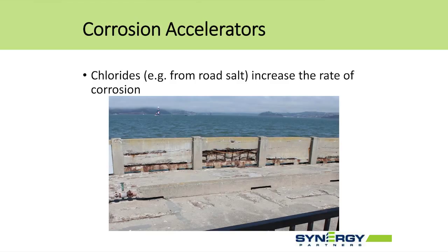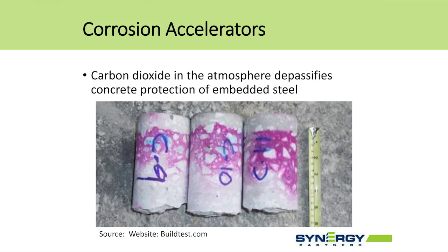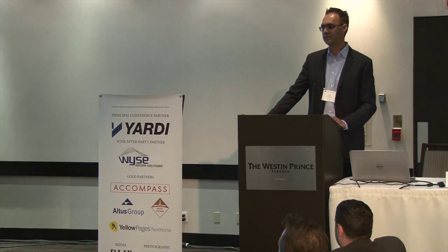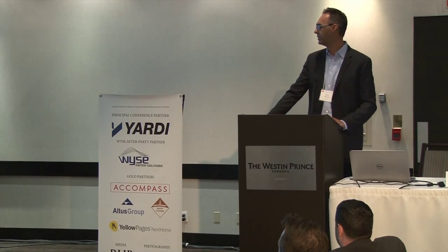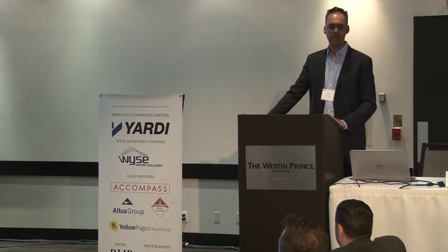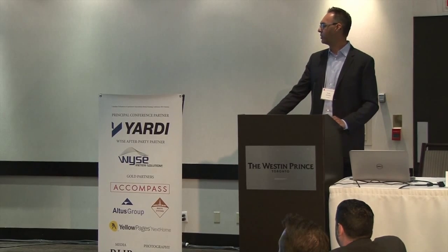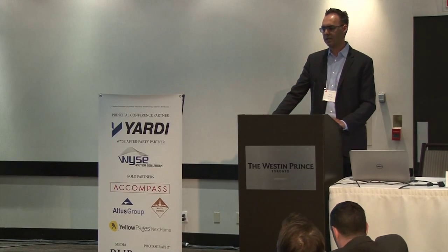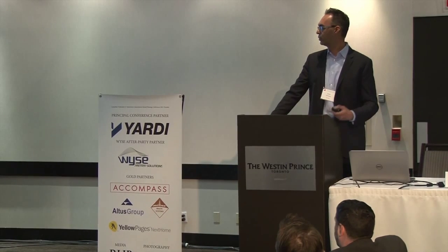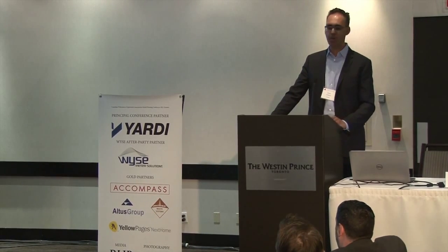Another process that you might not be so familiar with is something called carbonation. This is where carbon dioxide within our atmosphere can get into concrete and depassivate the natural protective cover that concrete provides on steel and cause corrosion as well. Now that's a little bit more complicated. There's a lot of debate in the industry about how effective or how important this is and how relevant it is to the degree of corrosion. But our experience has obviously been that carbon dioxide does cause steel to become depassivated in concrete.